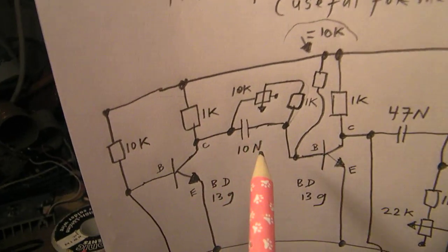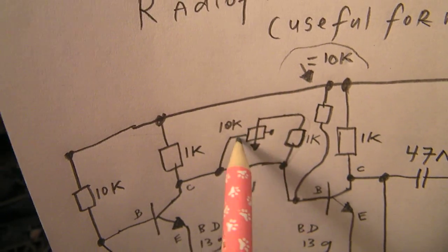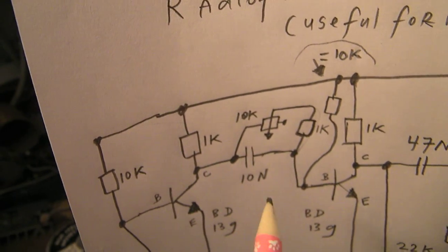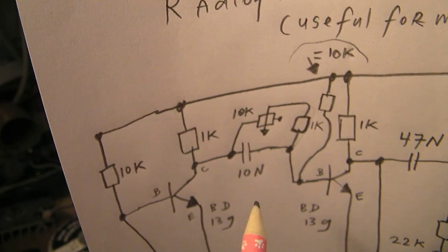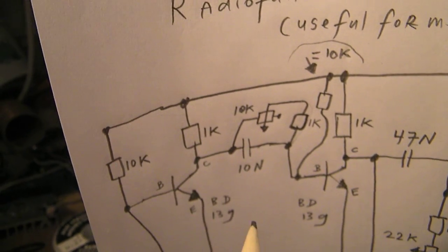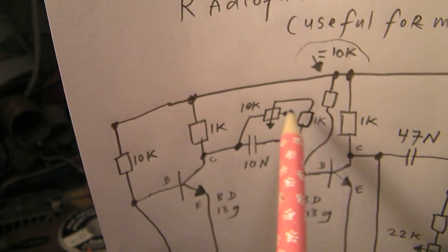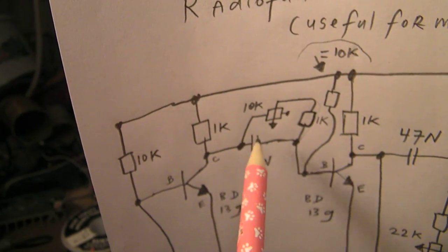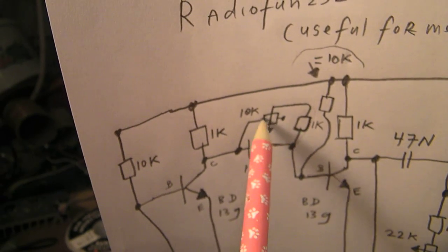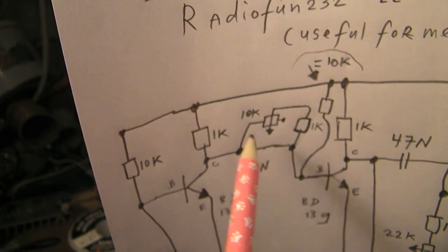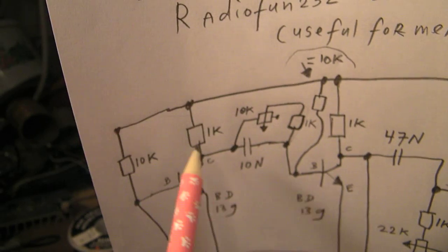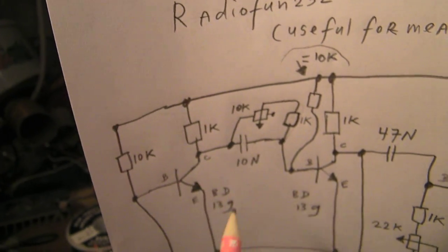This is a way, with this potentiometer and that resistor, to change the properties of the capacitor. In fact, you are shortcutting it here with this potentiometer. That makes the RC time, so the frequency time, change.